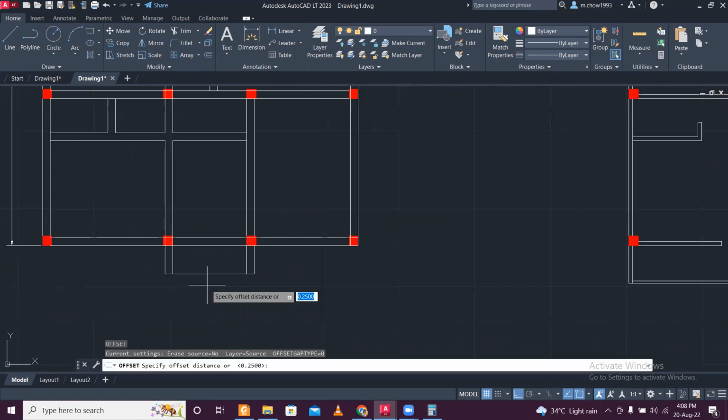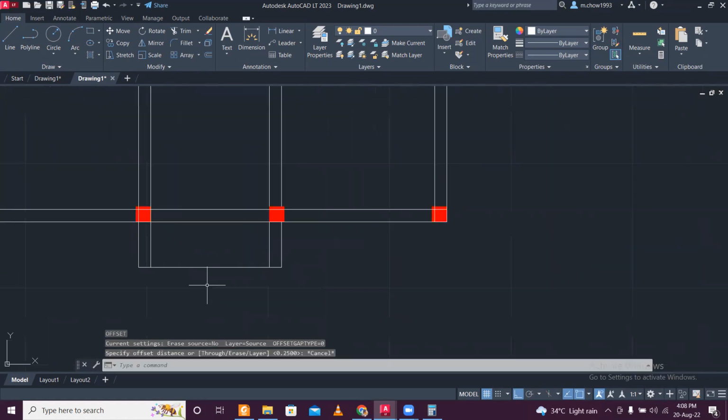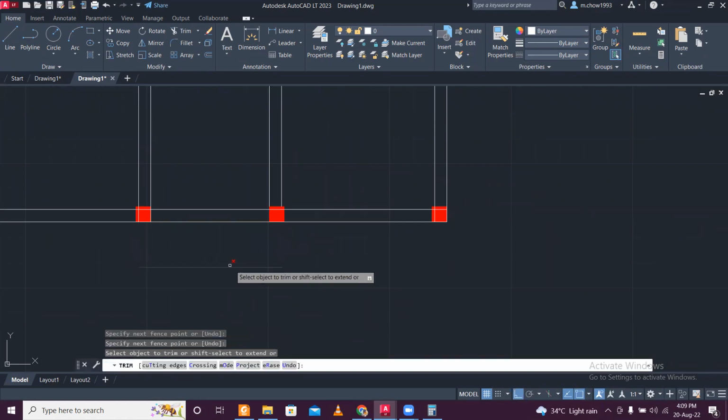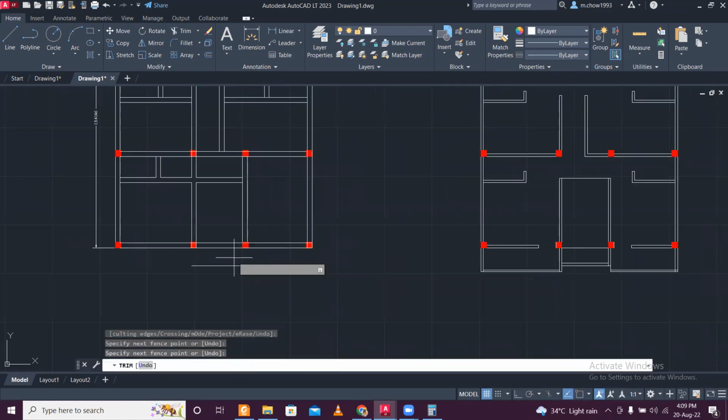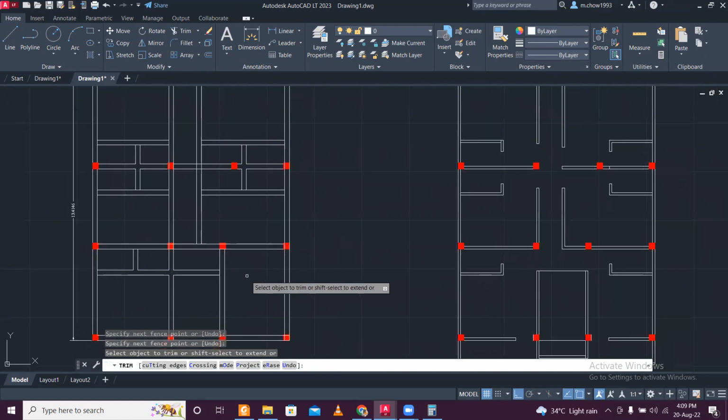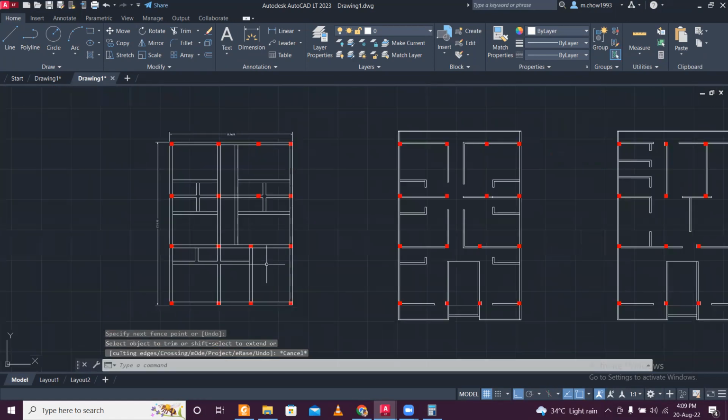Then there will be another beam here, but in the plinth level it will not be there. It will be in the mid landing portion. So in the plinth level, you don't need this. This beam will be there in the mid landing. We'll measure and put the coordinates separately for the mid landing beam. That will be a separate case when we provide the staircase.